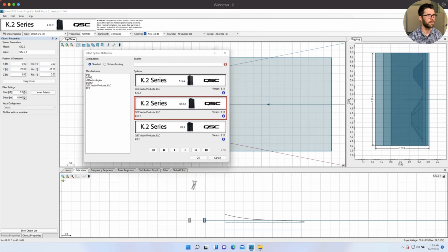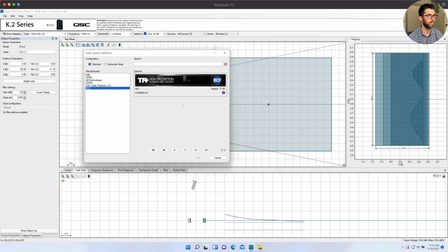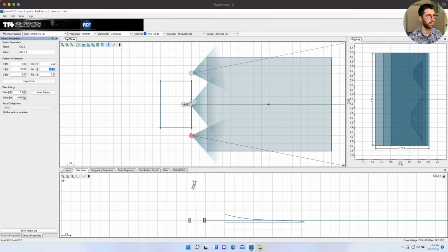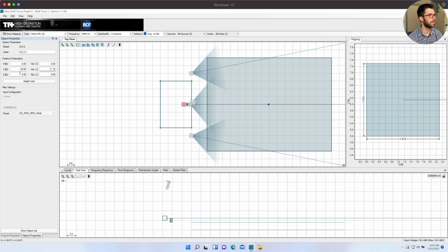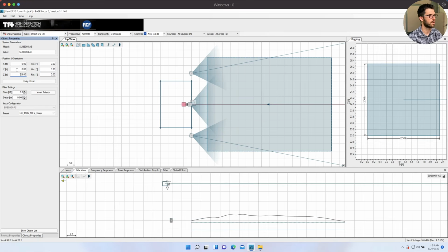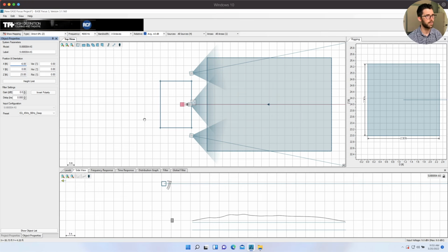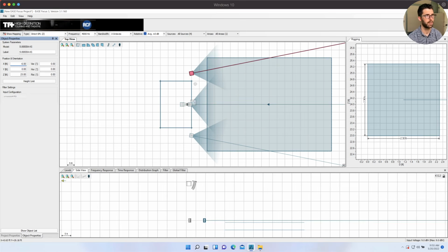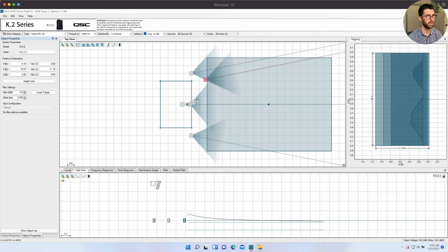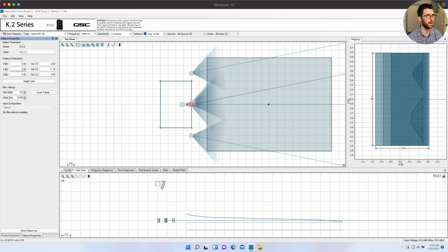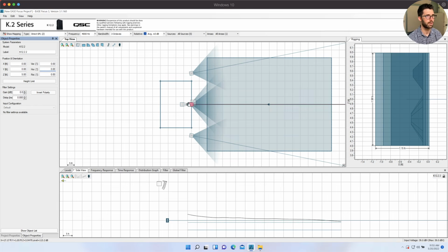Now I'm going to add a subwoofer. Put it here behind that array. 23 feet in the air. 6 foot behind, so it's sitting right behind that array, and I need my center fill speaker. Command C, Command V. And sometimes it's easier just to type in the values. I know it's 0 on my x-axis, 0 on my y. Let's put it right on the origin, 0 out the horizontal splay. It's 5 feet in the air, so it's good to go.